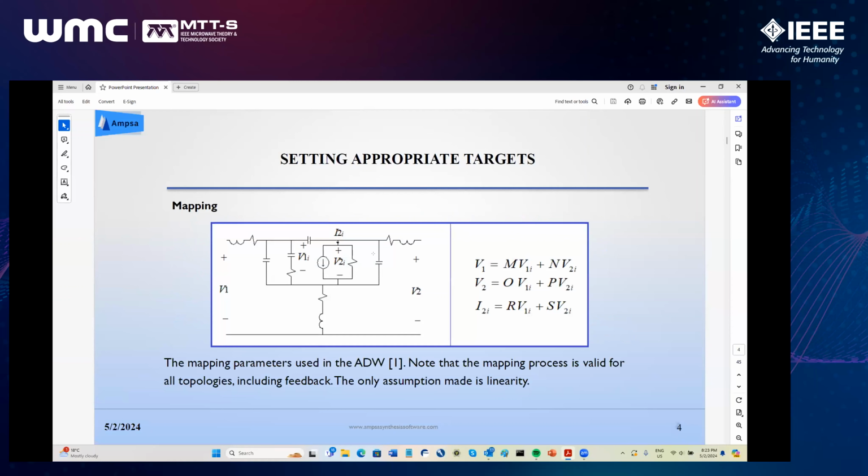Now we've seen the intrinsic model of the transistor before. What's different here is you can assume the load for this intrinsic device is a cascade, and then you can hope to embed it as the inverse cascade. But in generality, you need something more. So what's happening here is you have a mapping. You map the intrinsic output voltage, the intrinsic driving voltage, to the external voltages, and you can do it with a mapping like this. So basically, the voltages are mapped by mapping coefficients to the intrinsic quantities.